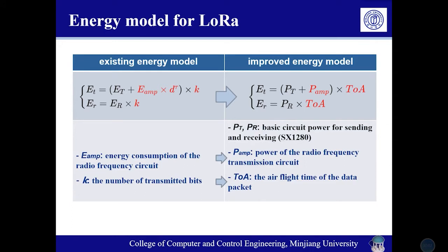To address the problem, first, we needed a suitable model which could be used to evaluate the energy consumption of 2.4 GHz LoRa communication. So, we redefined the existing model. The calculation of energy consumption based on radio frequency circuit power (PM) is more suitable for discrete regulation in practical applications. Meanwhile, based on the dynamically adjustable transmission rate in LoRa communication, we use the transmission time to replace the number of bits in the existing model.